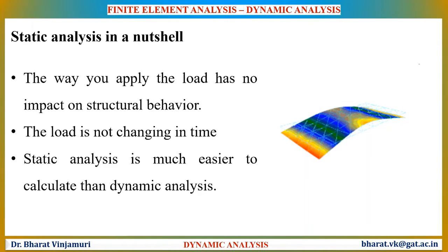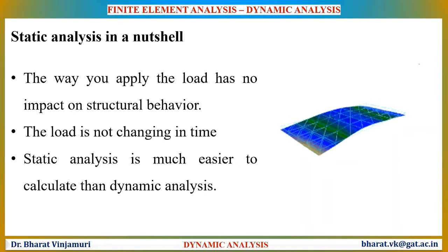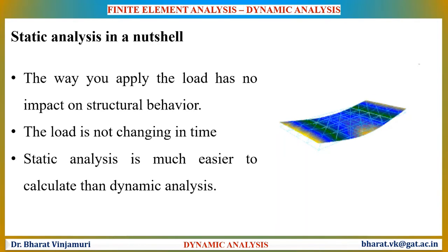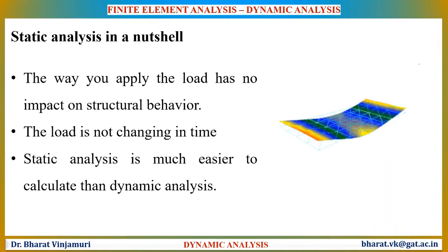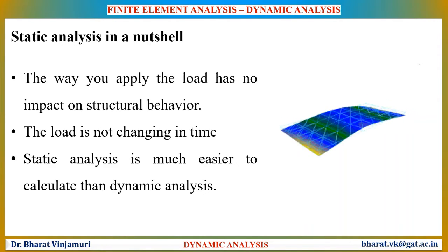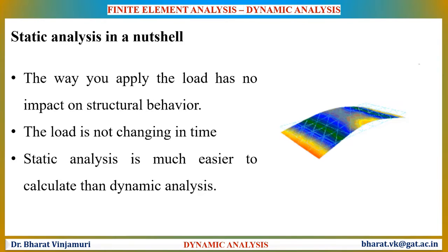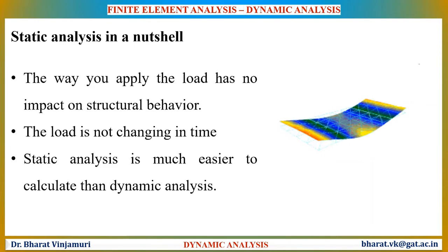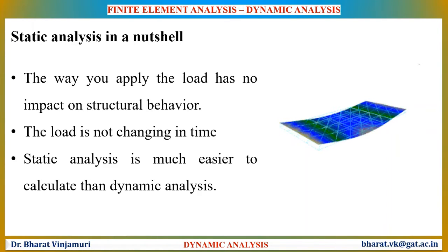Before we completely understand the dynamic behavior of structures, let us understand the static part of it. During static analysis, it doesn't matter how you apply the load. It is assumed that the load is applied extremely slowly. This means that the way you apply the load has no impact on the structural behavior. The load is not changing in time, it is just there. Static analysis is much easier to calculate than dynamic analysis and requires less sophisticated equations.